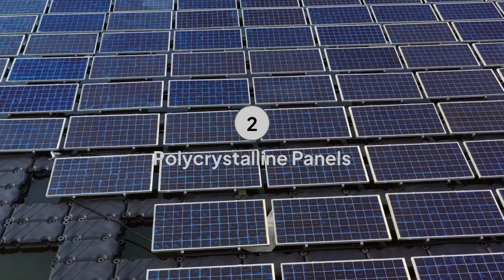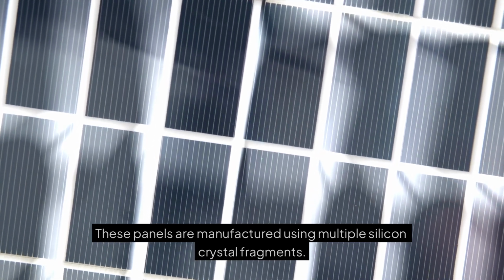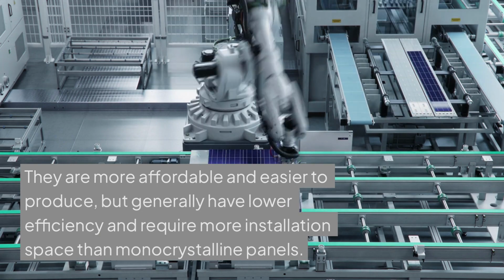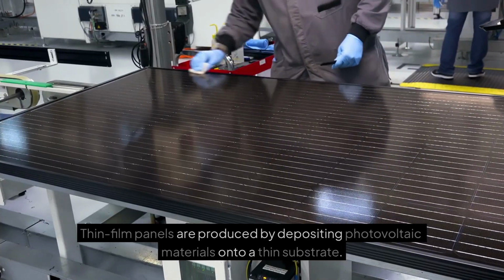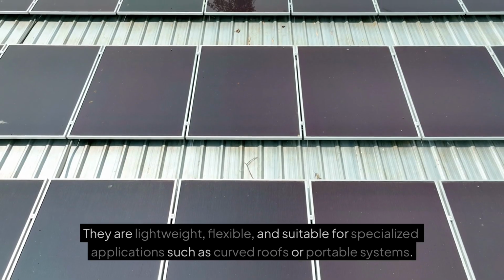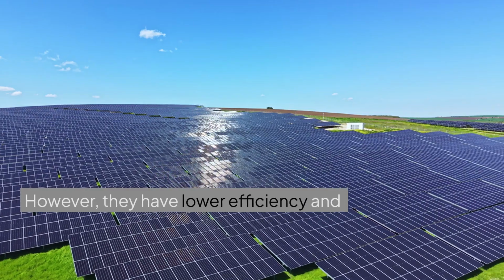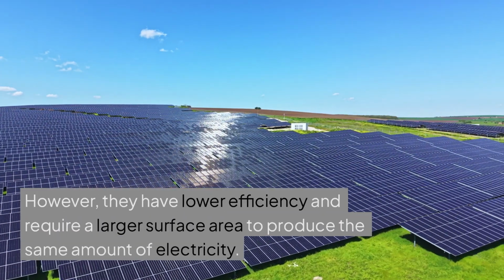Polycrystalline panels. These panels are manufactured using multiple silicon crystal fragments. They are more affordable and easier to produce, but generally have lower efficiency and require more installation space than monocrystalline panels. Thin film panels. Thin film panels are produced by depositing photovoltaic materials onto a thin substrate. They are lightweight, flexible, and suitable for specialized applications such as curved roofs or portable systems. However, they have lower efficiency and require a larger surface area to produce the same amount of electricity.